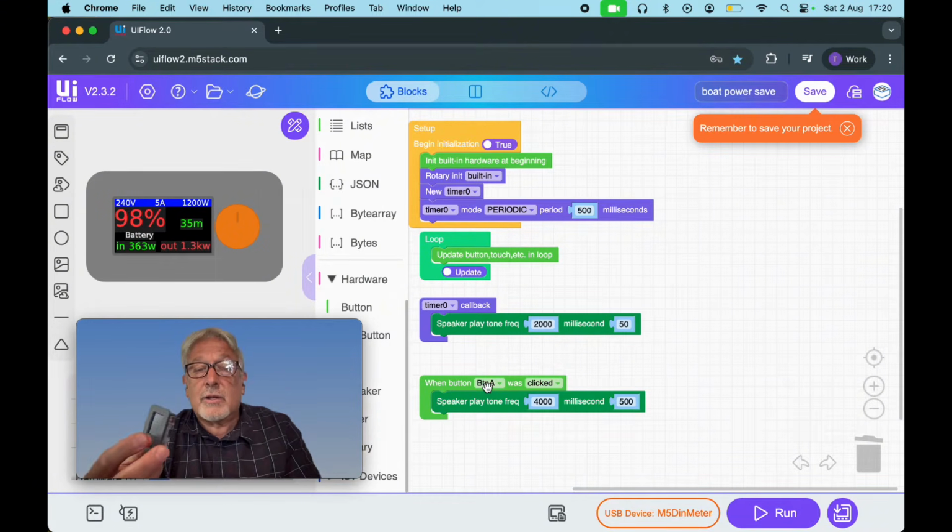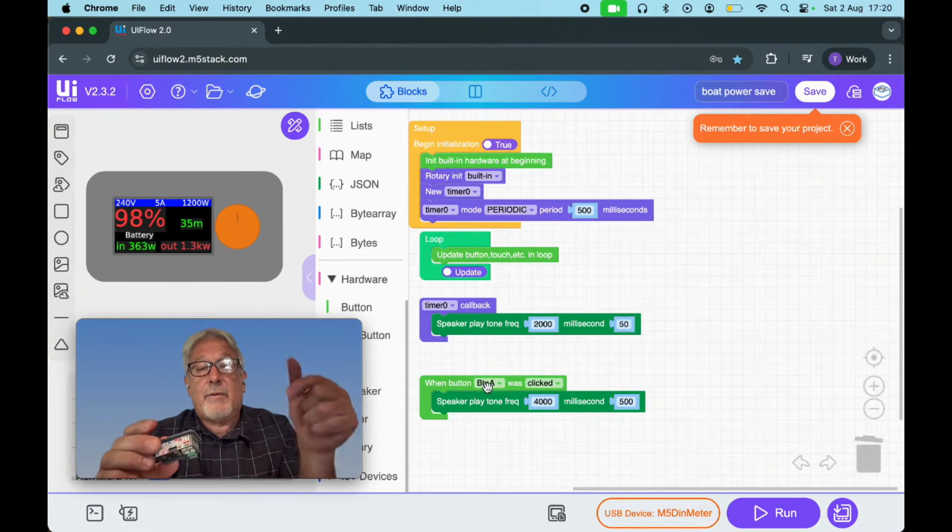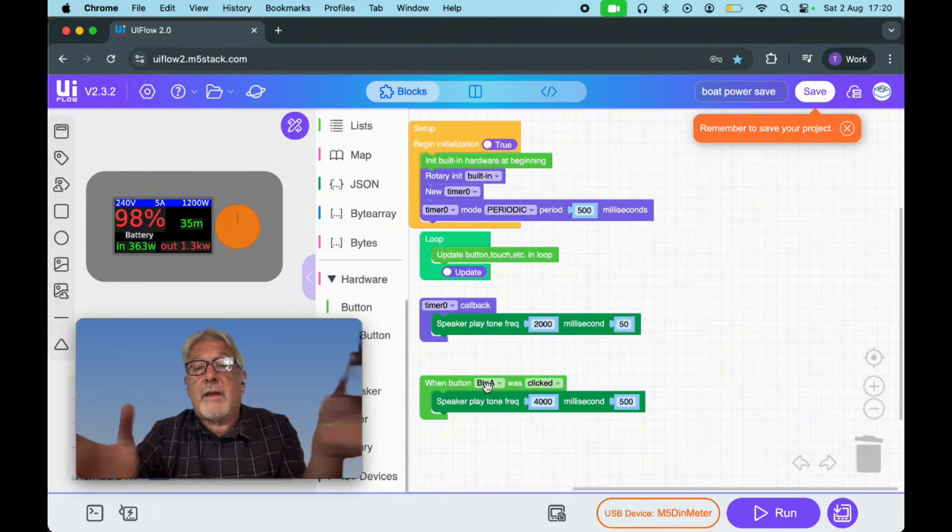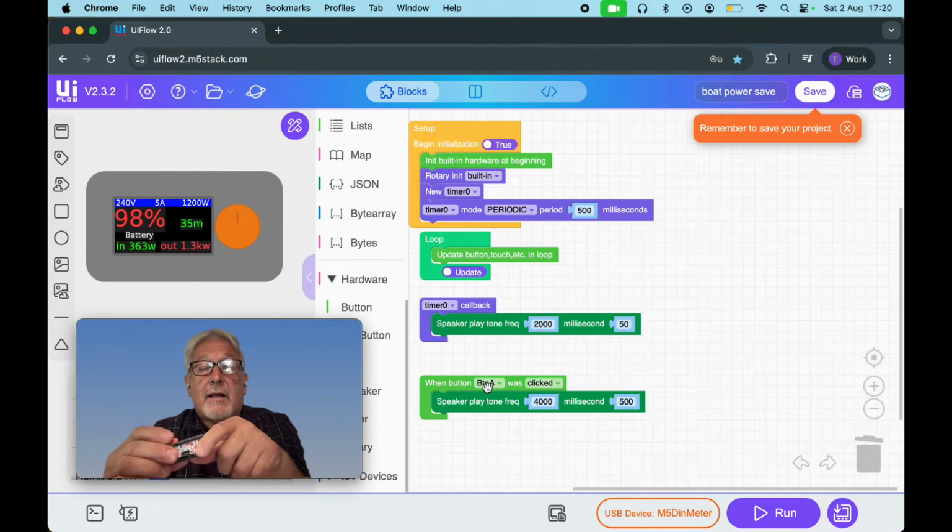So this is not going to be a point of failure of the boat. The failure mode is it works as an existing system, so you can plug stuff in, it just works. This only takes over if you power it up. So if I turn off the 12-volt circuit that's running all these, then everything will just carry on working. That's the first failure mode.